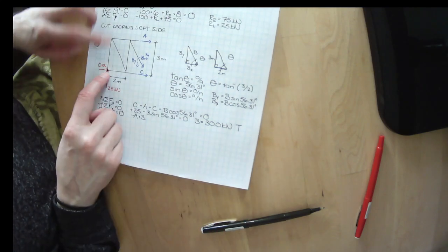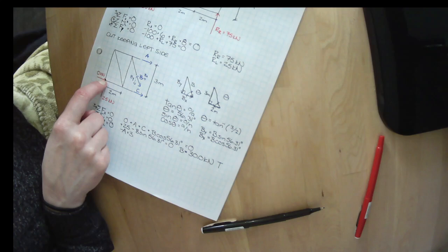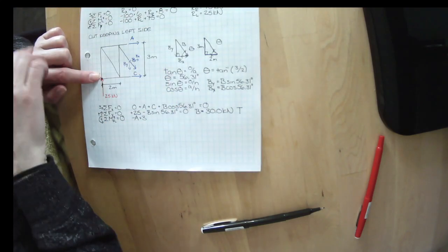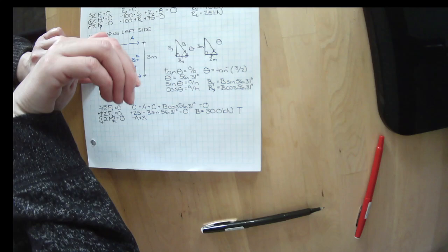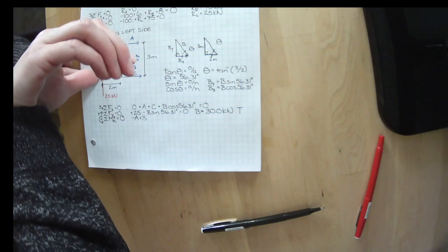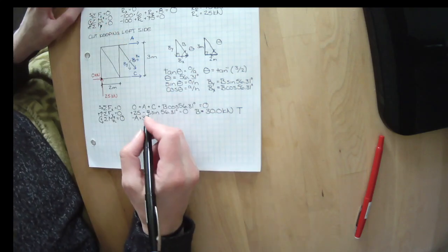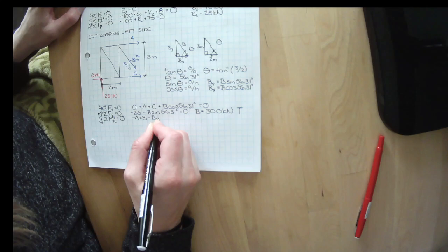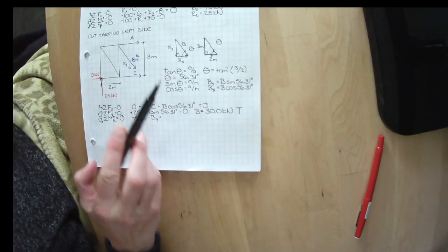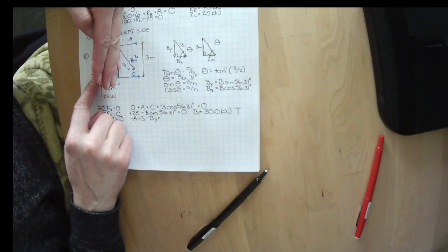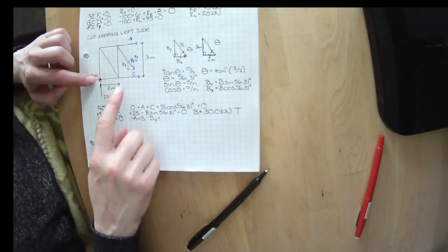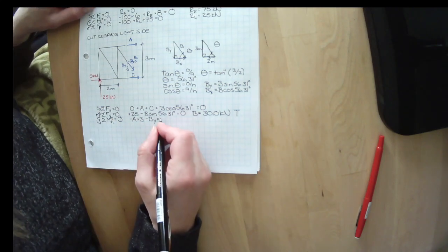If I put my thumbtack right here and push right here, BY is causing the paper to spin in that direction. Or if I curl my fingers, BY is causing it to spin like that, point my thumb down, it's negative. I've got minus BY times, and the closest BY comes, it's acting on this plane right here, the closest it comes is 2 meters.